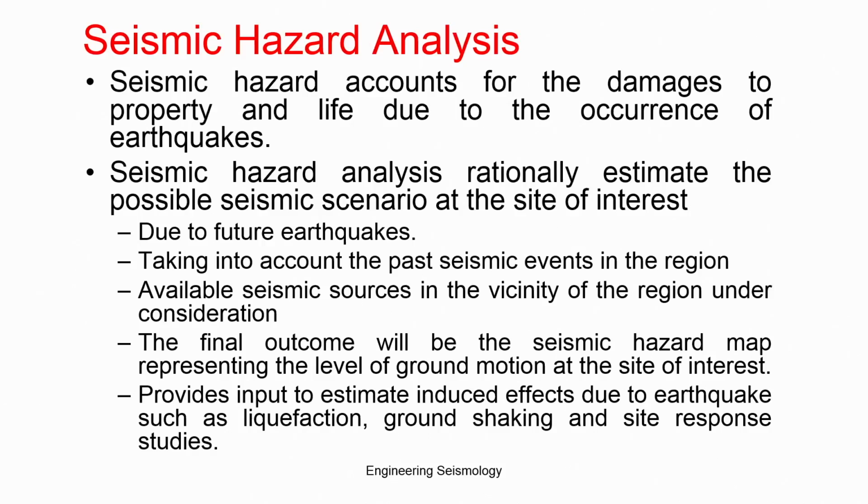So, why do we need to estimate a hazard basically? The seismic hazard accounts for the damage of property and life due to the occurrence of an earthquake. The seismic hazard analysis rationally estimates a possible seismic scenario at a site of interest due to a future earthquake, taking into account the past seismic events in the region and the available seismic sources in the vicinity of the region under consideration. The final outcome will be a hazard map representing the value of PGA at the site of interest, or intensity if risk assessment is required, or duration if duration related parameters are of interest.